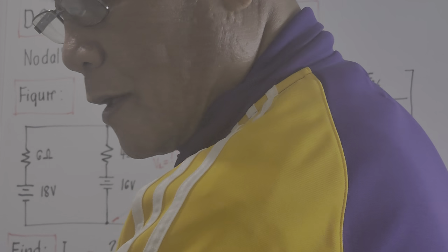By using the 18 volt source, the voltage across this is 6.54. Since this one here is in parallel with this, whatever voltage appears here will be the same as this one. We could compute now the current passing through the 24 ohm load due to the 18 volt source, and that current is 0.2727.